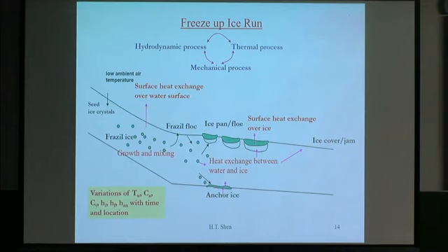During the freeze up, when they're moving to downstream, at the same time you get more and more ice produced, so the concentration gets higher and higher. Somewhere it will jam, and that is starting off the main ice cover, or ice cover in the mainstream of the main channel.